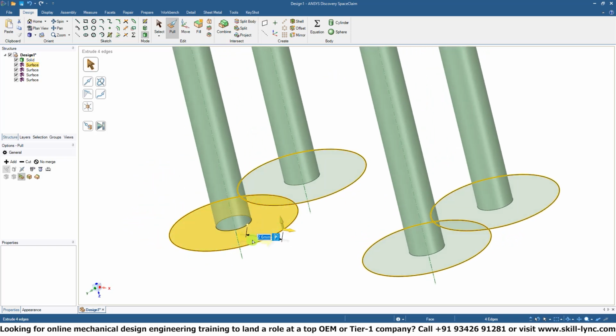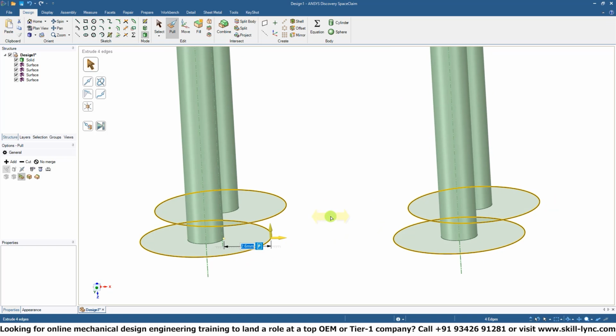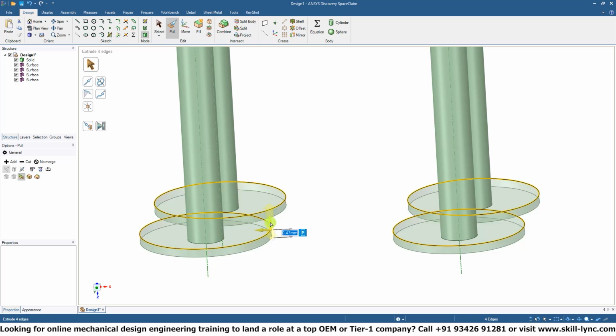But this pretty much gives us just a surface area. It's not exactly 3D. So when we send this model to a 3D printer, it would have an issue because it won't be able to detect it. This area has technically a 0 thickness, which obviously makes sense mathematically because we're working in 2D rather than 3D when we're discussing this. But in a real life application, the 3D printer needs to know what thickness of the layer to target.